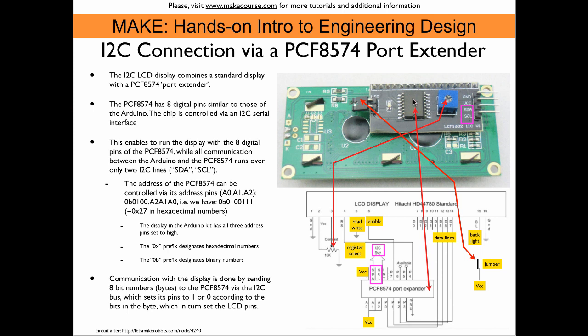So with this module, you can not only drive such an LCD display, but you can use it for all kinds of purposes where you don't have enough digital pins on the Arduino. Here we use these 8 pins that this module has to control the data lines, and of course the read, write, enable, and the register select lines.